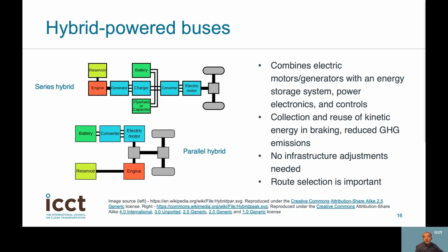The higher complexity of a hybrid bus implies a higher cost than conventional ICE buses. On the other hand, compared to fully electric battery electric buses, hybrid buses do not require an external electrical connection to charge the battery, and there are no infrastructure changes required when transitioning from diesel technology. Kinetic energy is recovered and used to recharge the battery onboard hybrid buses during braking events. Hybrid power may allow for engine downsizing and even partial electric-only operation, including engine shutoff when idle.